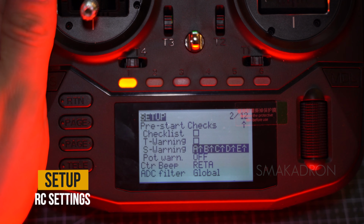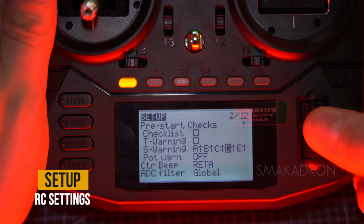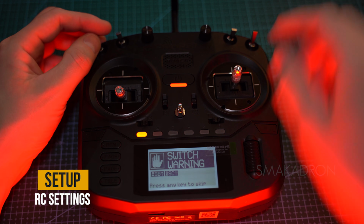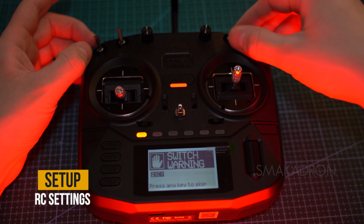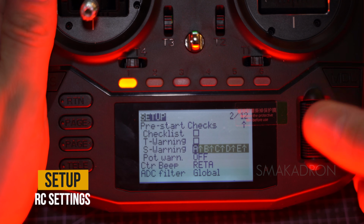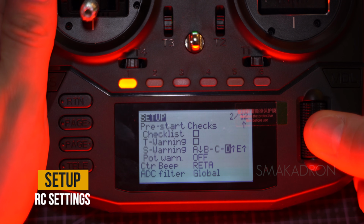Switch warning is used to check the positions of all configured switches when the radio is turned on. This warning helps ensure that all switches are in the correct position for safe startup and operation of the model. Here, the switches and their required positions are indicated for you to be allowed into the main menu. Most flight controllers already have a built-in system that prevents the motors from starting if the radio is turned on with the armed switch in the armed position. I have disabled this check for myself.